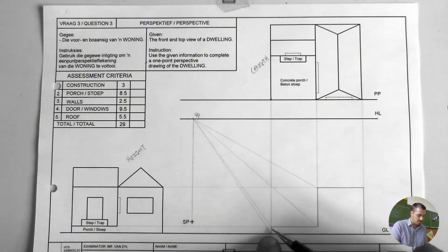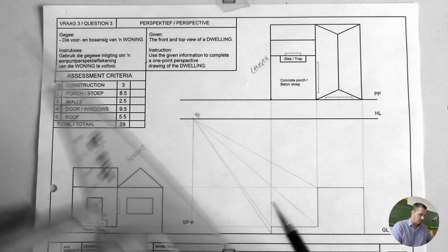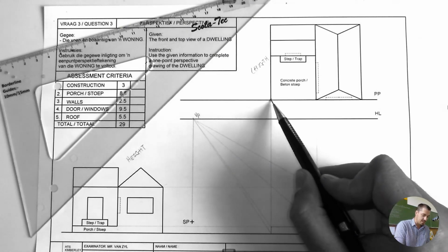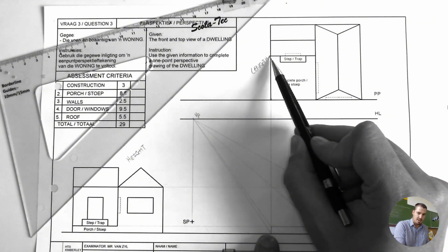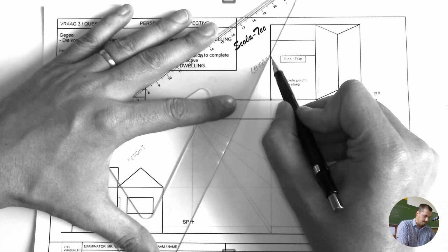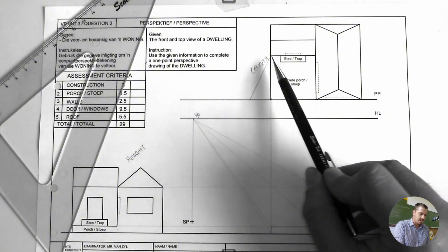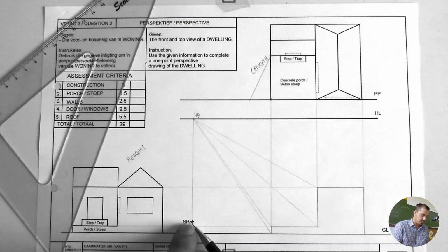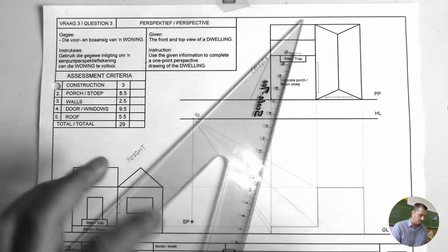Alright, in order to determine how far, the length the drawing is going to be, you can see there is the starting point that I have. That point goes all the way onto the back of the house, which means that point goes to the SP. And this is where you have to realize all the lines on the top view have to go to the standing point, and then stop on the picture plane before you bring it down.